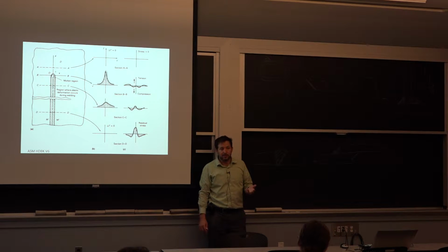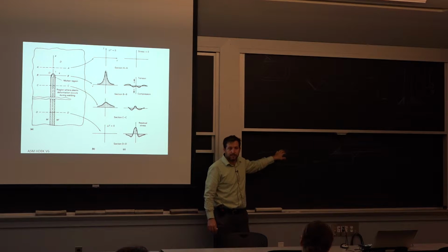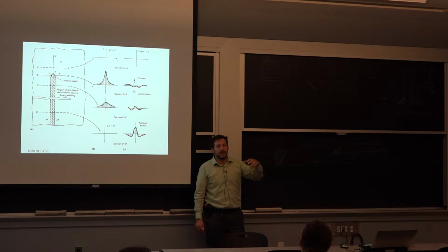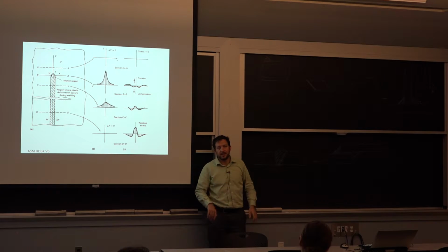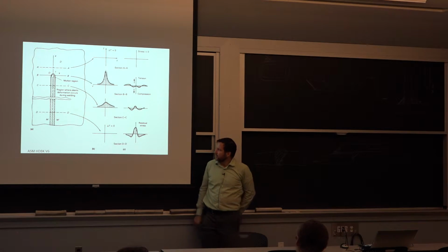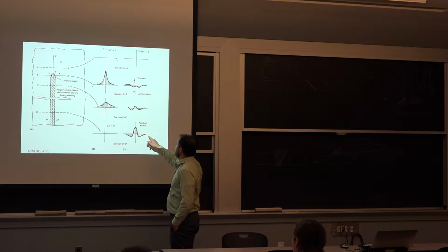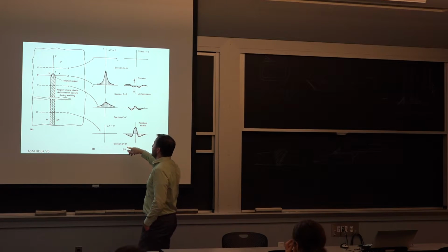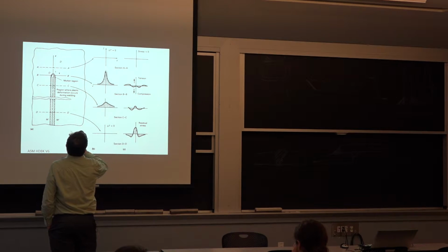If you have pre-tension, then you know that your capacity is going to be reduced in cyclic loading because sometimes you can be very close to the yield strength on the surface here. So if you're already close to yielding, any force gets you over, and then you start having this accumulated damage very quickly. So there's a lot of analysis done in terms of what happened to the residual stresses. We're looking here into different directions. Probably the most significant one to think about is,